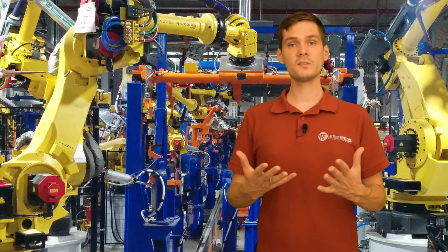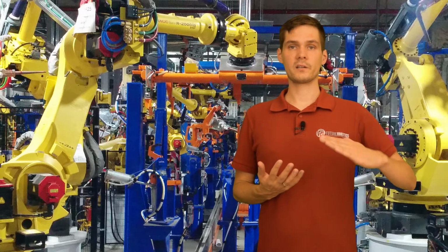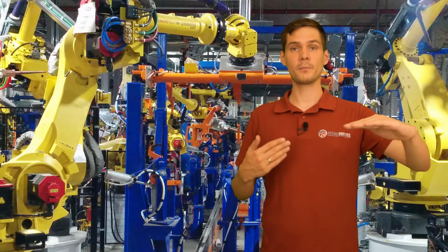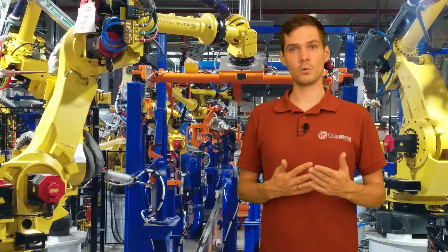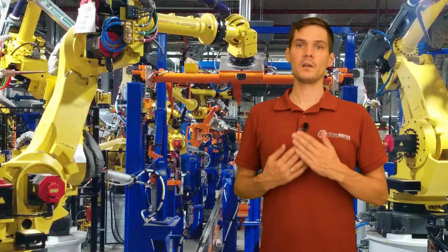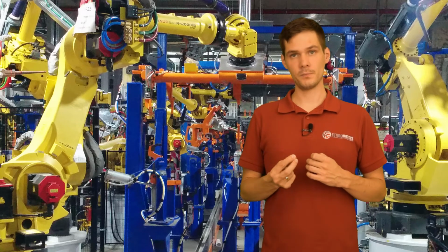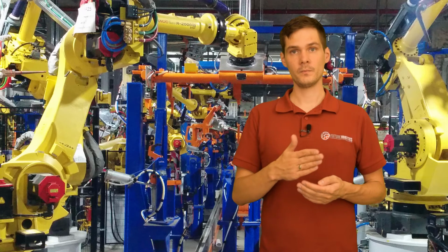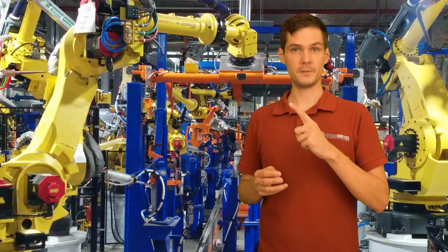So what is the frame? Basically you're going to tell the robot, you're going to define a 3D plane for him, and you're going to measure the distance from the robot to that plane, and that's how the robot will know where he's working at. But before you do it, you need to have a pretty accurate TCP, because you're going to use that TCP to teach the frame. If you don't know how to teach the TCP, check out my video about the TCP.